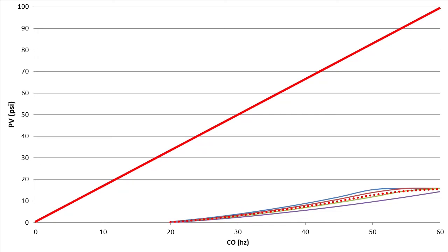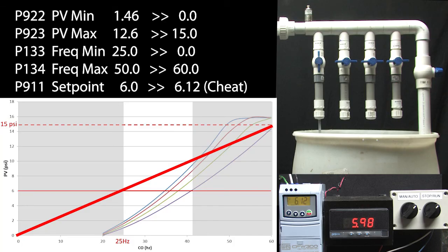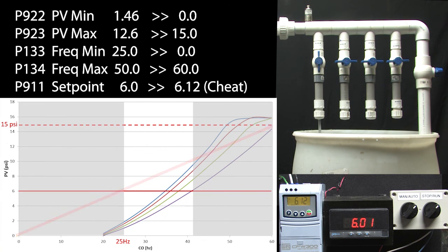Now our line isn't close to our process at all, is it? Would that have given us such good results? Well, no, it would have been way off. Regardless, even though we didn't use the actual system curves, we're still able to get a reasonable tuning regardless of load. Pretty cool. What if you did plot your system's performance and you got something odd like this?